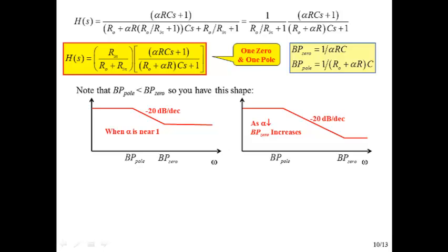And so clearly, as I change alpha, the zero location changes a lot. And I also can figure out from this that the pole is lower than the zero. So I start flat, since there's no single S up in the numerator. I start flat. I hit the pole first, so it breaks and goes down. Then I hit the zero and it levels out.